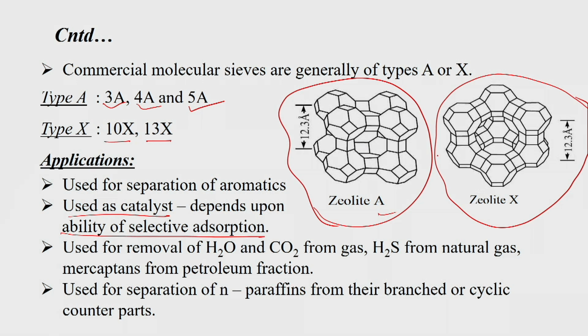The different openings are like this, this is the opening of one zeolite. So, it can trap a particular material with this particular hexagonal shape. Here also this is one opening, and on this side there is another opening. So, based on the opening size, the particular target component will be trapped inside, and whenever we do any pressure swing or temperature swing desorption, it can release very easily.